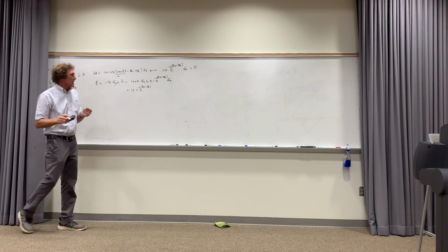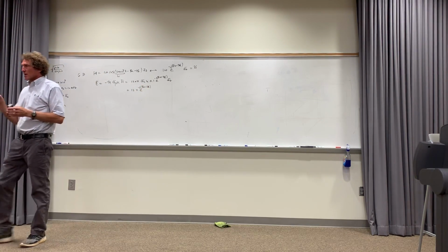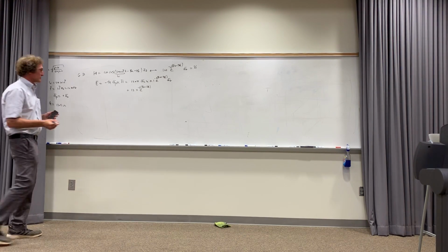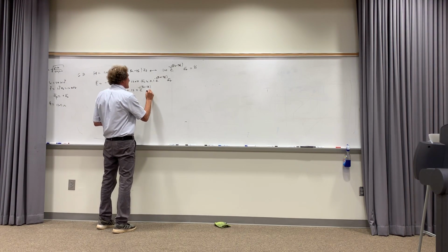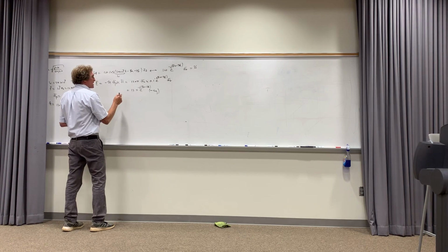Once I have that, I do the cross product. What is AX cross AZ? Think about it now. Minus 1. That's right, it's X, Y, Z, and if you go from X to Z, you're going the wrong direction, it's negative, so it's minus AY direction. And that would be the E field.